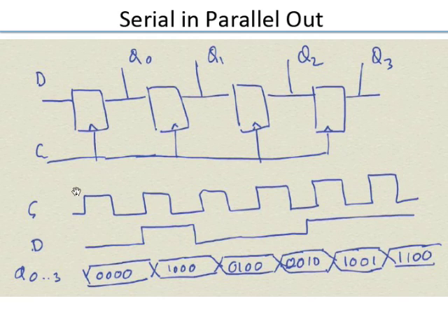So what you do is, if you want to set up a particular bit pattern, let us say I want to have the bit pattern of 1100, then over a number of clock cycles you can toggle D such that you have a pattern 1100 out here, and then you are done. So you have 1100 pattern now set up across this. So you see it has taken basically 4 plus 1, 5 cycles to set up a particular pattern. Basically it takes 4 cycles to set up any pattern you want.